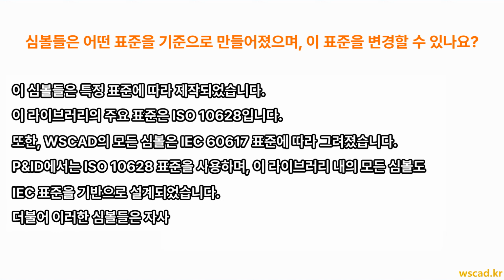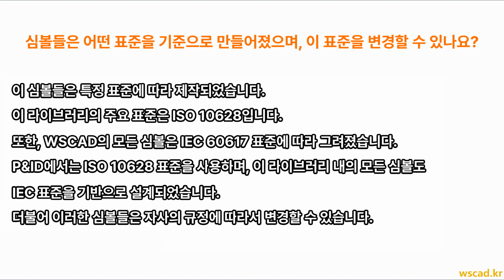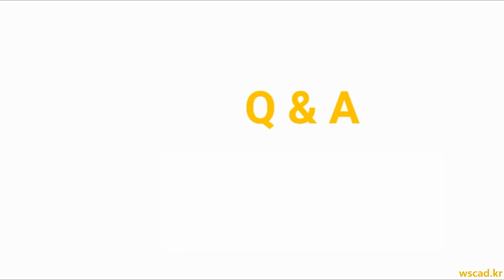So question number 2, by which standard were these symbols created, and can these standards be changed? So we can check, the main standard of this library is ISO 10628, and all these symbols in WSCAD are drawn according to standard IEC 60617.